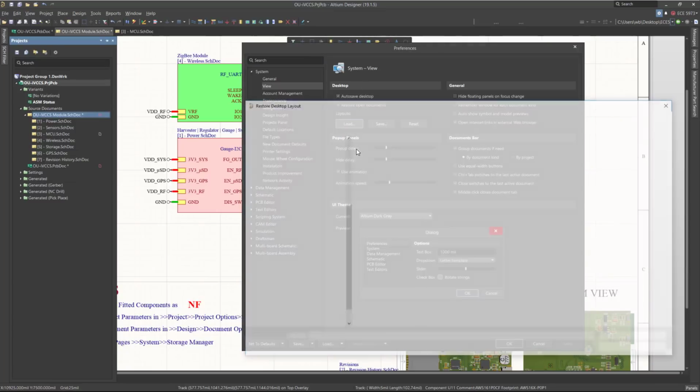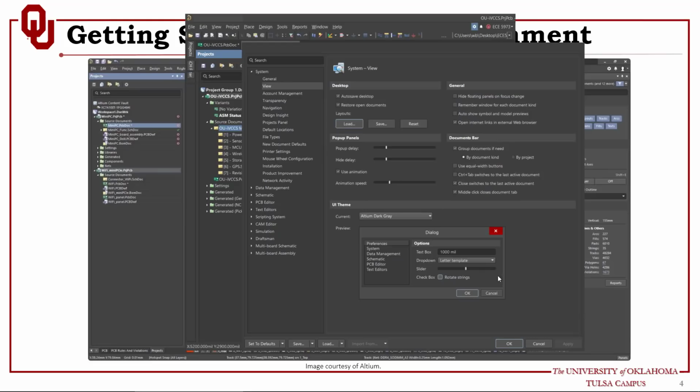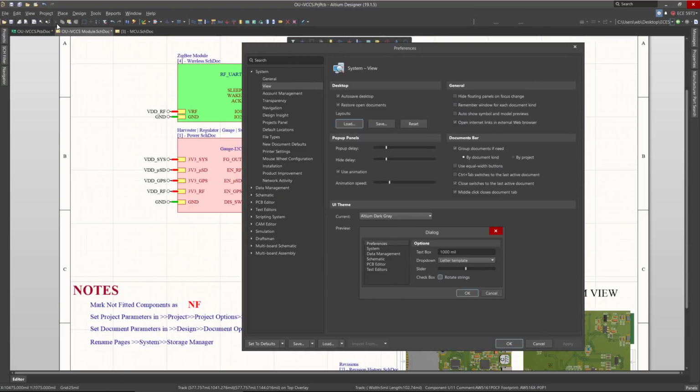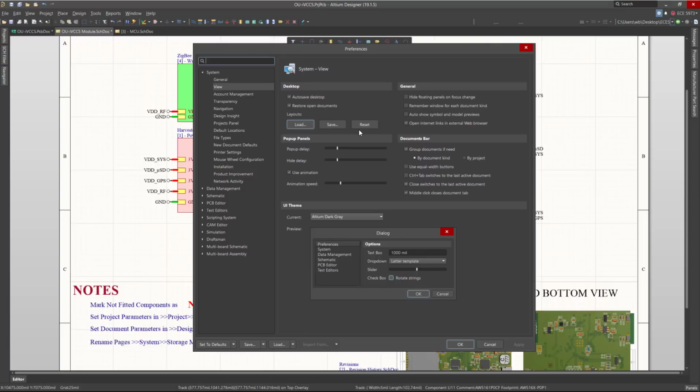You go to load and click on load, and Altium will automatically restore. Now Altium restored, as you can see. If you have all these closed, Altium will open them again. So you have a configuration of the Altium environment set based on your convenience, and you don't have to do it every time. For instance, if you put shortcuts, or have some comments here on the status bar,